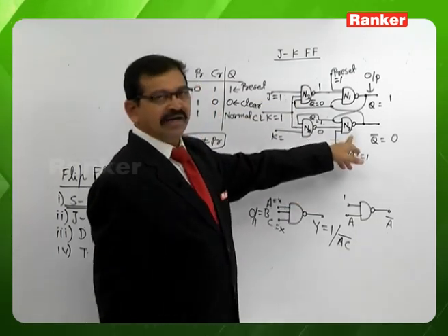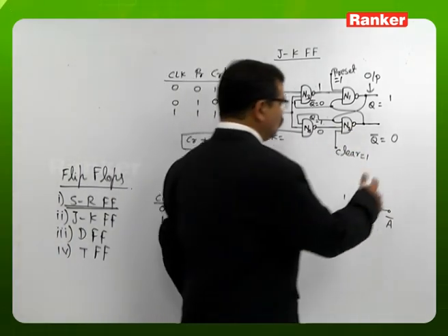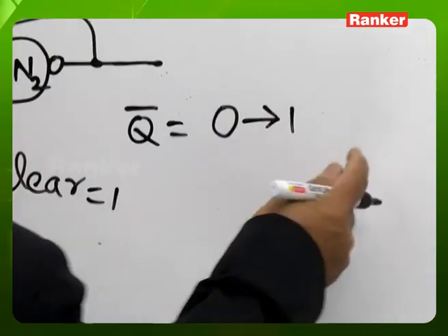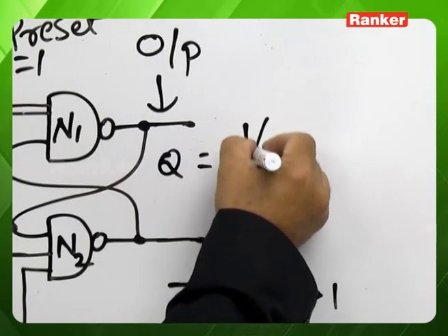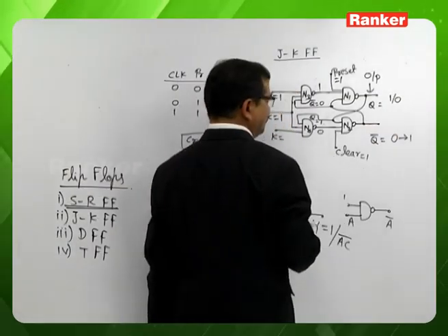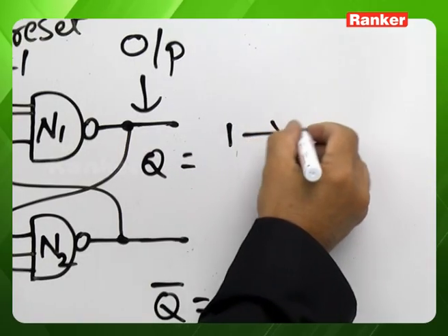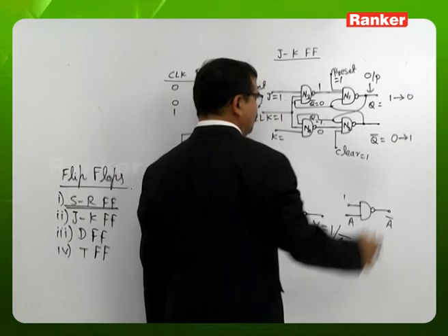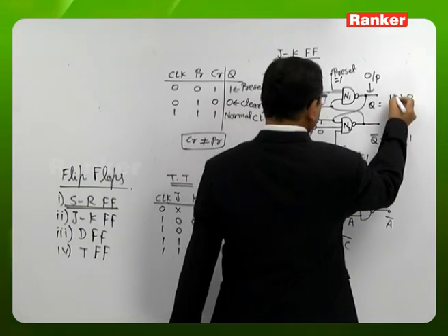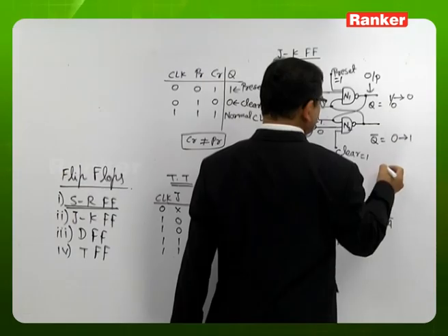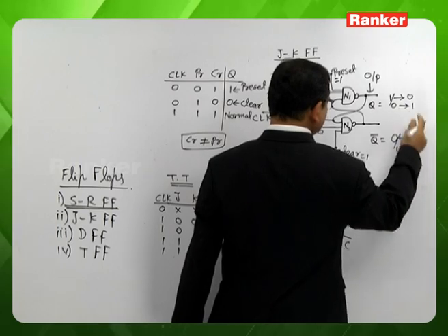Hence, we are reading the NAND gate N2 first. One of the inputs of N2 is 0, so the N2 output is 1. Now all 3 inputs of N1 are 1, hence the N1 output is 0. So having the previous state as 1, we are able to read it as 0. Similarly, if before applying the clock signal the previous state is 0, it is possible to recognize the next state coming to be 1.